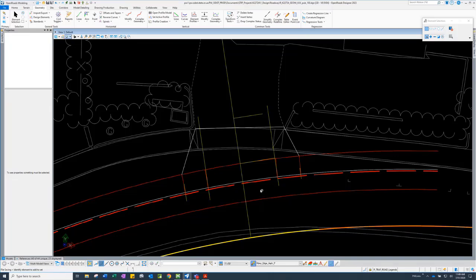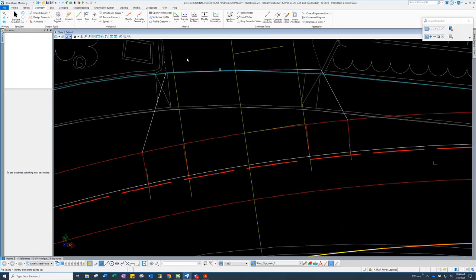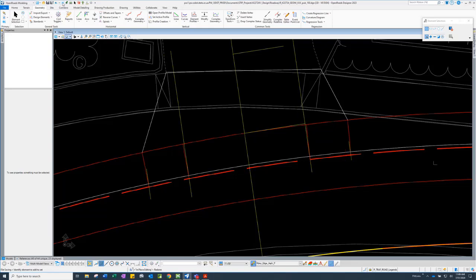Yeah, would you zoom in there and just right there, and now do an undo? Oops. Yeah, do an undo and then a redo, just so that we can see the lines move. Undo, and it goes. Should go back. There's one. Okay, and then you redo. Oh, that was too many undos. There. Redid. Okay, so we see that the edge of pavement point up in the upper right corner stayed fixed because it was snapped to the dashed line coming from the reference. That didn't move. But all of the sidewalk, the wing lines, those all moved.